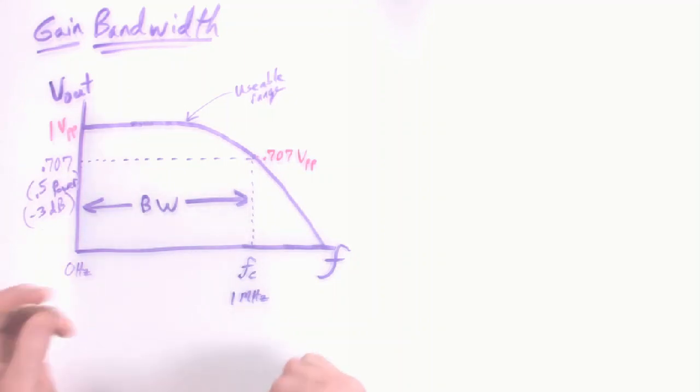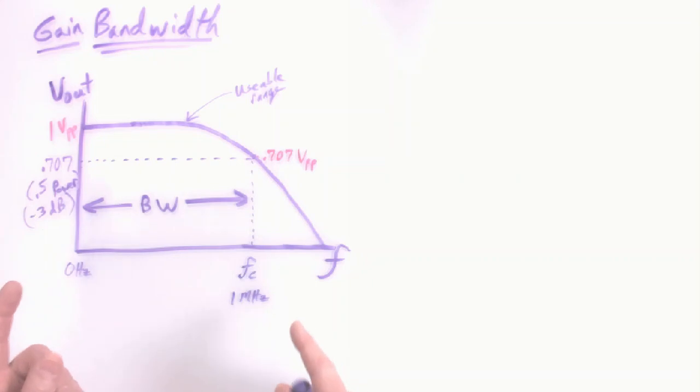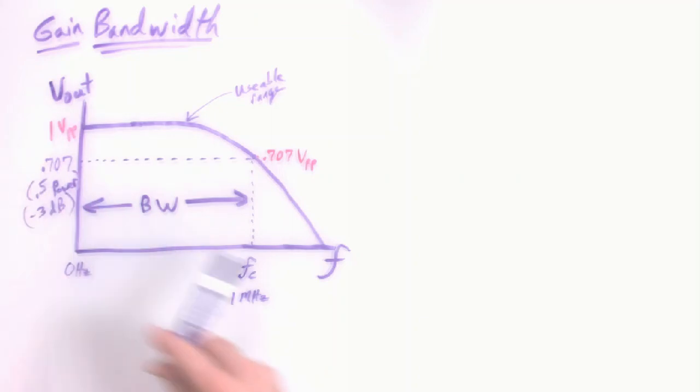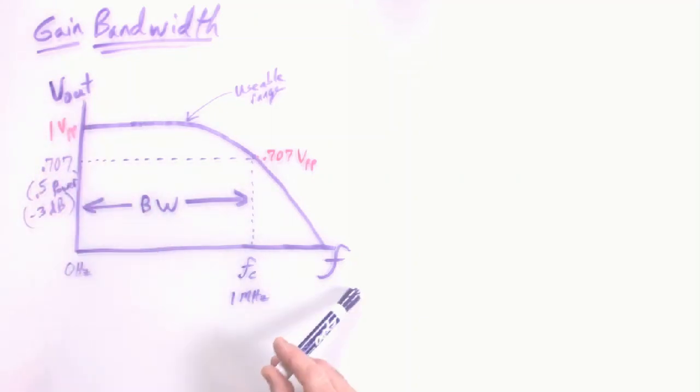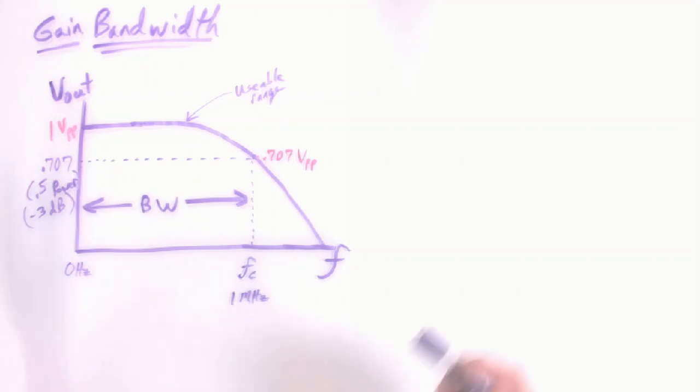in the YT oscilloscope mode that we're going to use at first, if you want to experiment with Bode plots later, we can. But just the standard YT mode, you're not going to get a plot of output voltage versus frequency. So what will you see on your screen? You're going to still be able to do this. Remember what you're trying to do. You have the op amp. Maybe you'll set it up as a voltage follower, which is a good plan if you're looking for bandwidth. Keep things simple. We've kept it very simple with our numbers, 1 volt peak to peak.